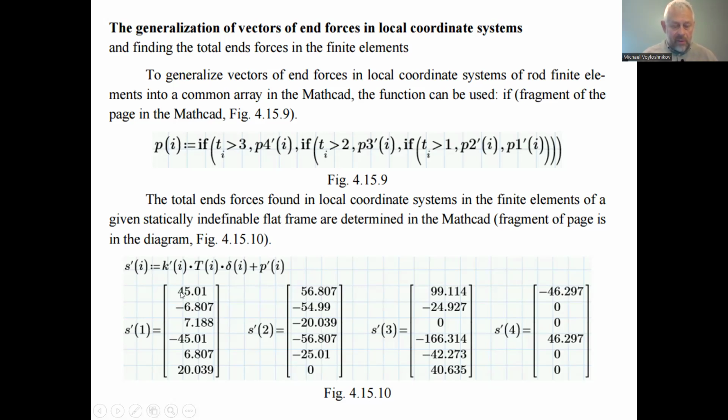So this is the longitudinal force, the same longitudinal force applied at the beginning and at the end of the first finite element, the vertical stand between node 1, the embedding of the stand in the considered mechanical system. This embedding has the longitudinal force in the local coordinate system associated with the finite element. The second one, at the end of the system, is this transverse force, and this is the bending moment at the embedding of the first finite element.